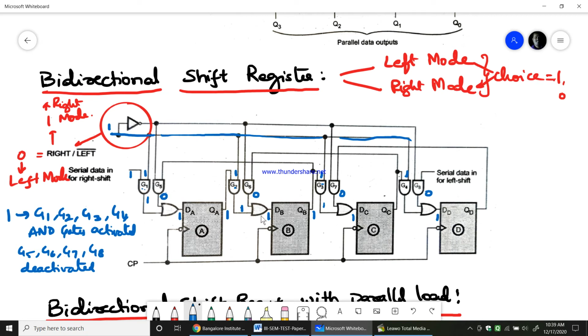While this one is shifting, meanwhile you also give other inputs here. That input keeps on shifting. Now if you give 0 here, this becomes 0 and that 0 will come here and the next data of DB will be 0. This 0 comes here. So this is how the shifting operation will happen.